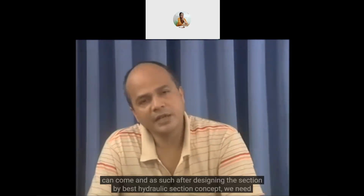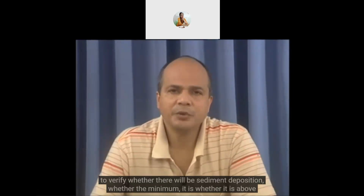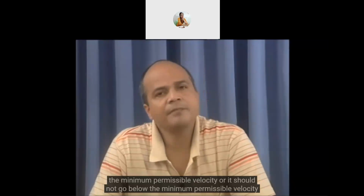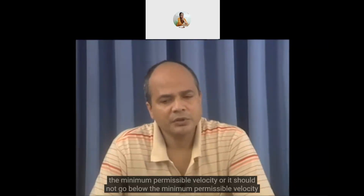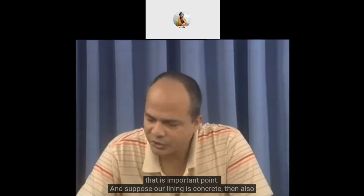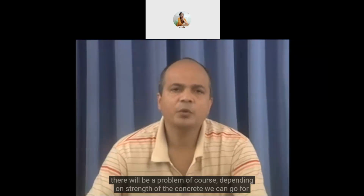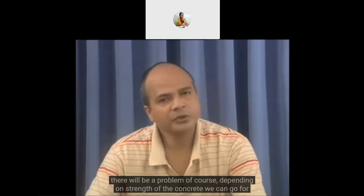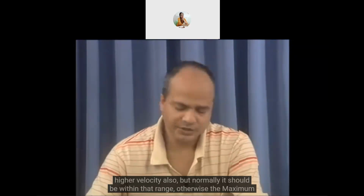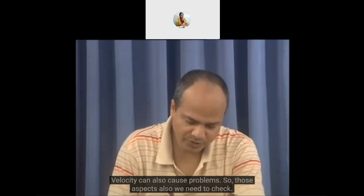after designing the section by the best hydraulic section concept, we need to verify whether there will be sediment deposition, whether it is above the minimum permissible velocity, or it should not go below the minimum permissible velocity. That is an important point. And suppose our lining is concrete, then also it should not exceed the value of, say, 3 meters per second. That should not be exceeded, otherwise there will be problems. Of course, depending on the strength of the concrete, we can go for higher velocity also, but normally it should be within that range. Otherwise, the maximum velocity can also cause problems. So those aspects also we need to check.